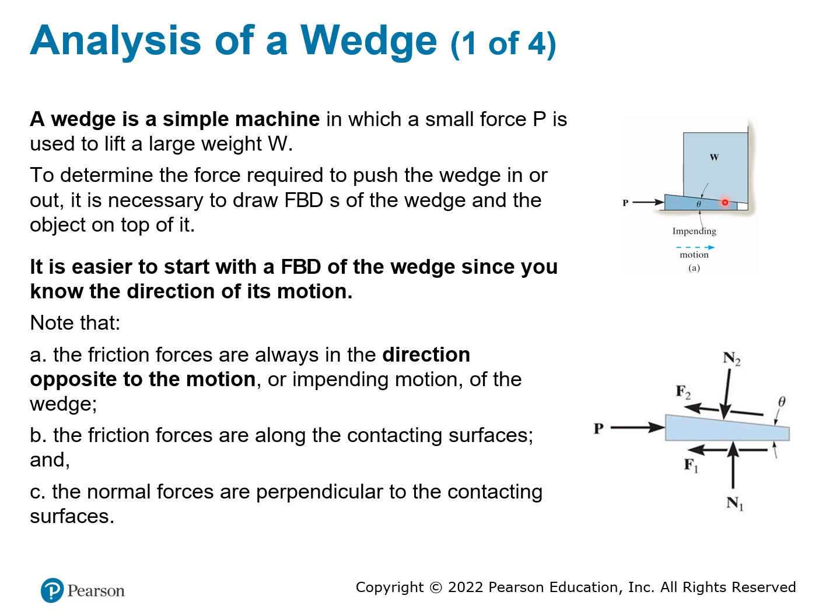So when you push in, you are making these things try to move to the right. The friction should go to the left. If you make a free body diagram of this object, which is this picture over here, you can see when you push in, the intended motion is going to the right, so friction has to go to the left. And remember, you have friction on both sides: one on the top between the object and the wedge, and the other between the wedge and the ground.